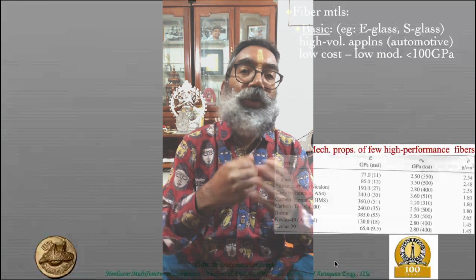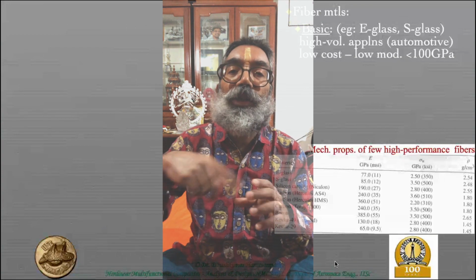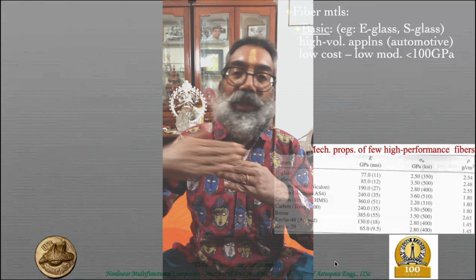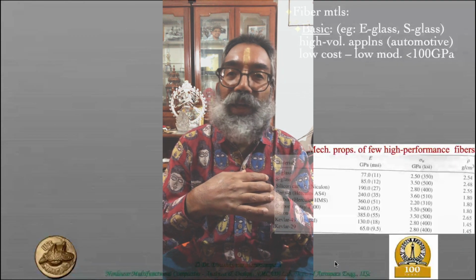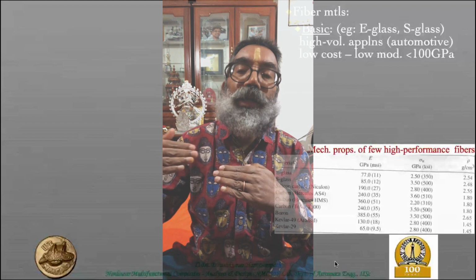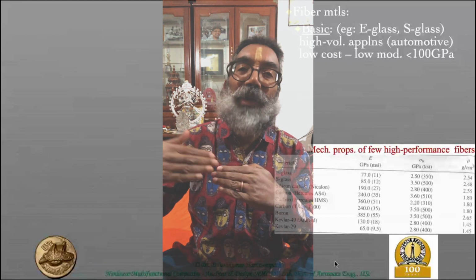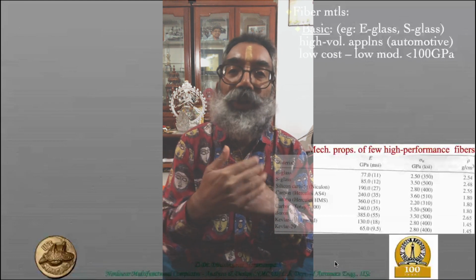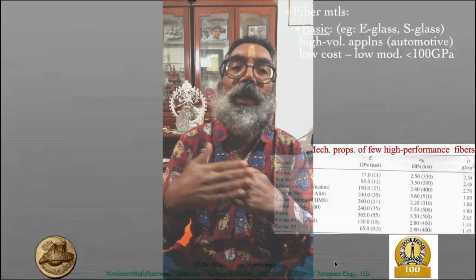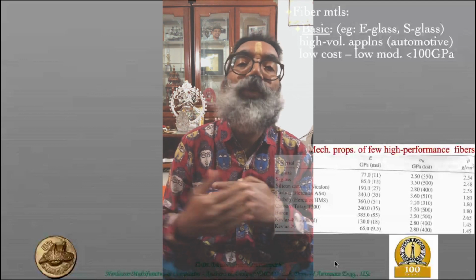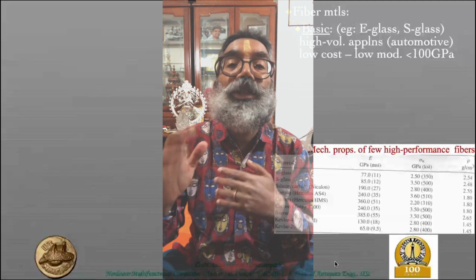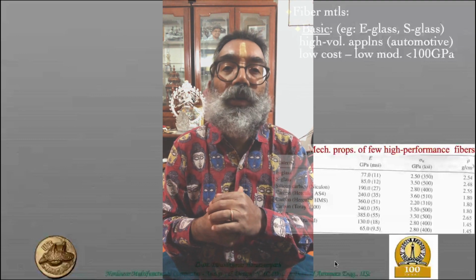The reason you are able to drill a hole in a metal, or shave off material in terms of machining in various forms, is that in the region where the material is being removed, the high temperatures result in almost a liquefied or plastic state of the material, which enables such machining. This is much more difficult in a brittler composite.